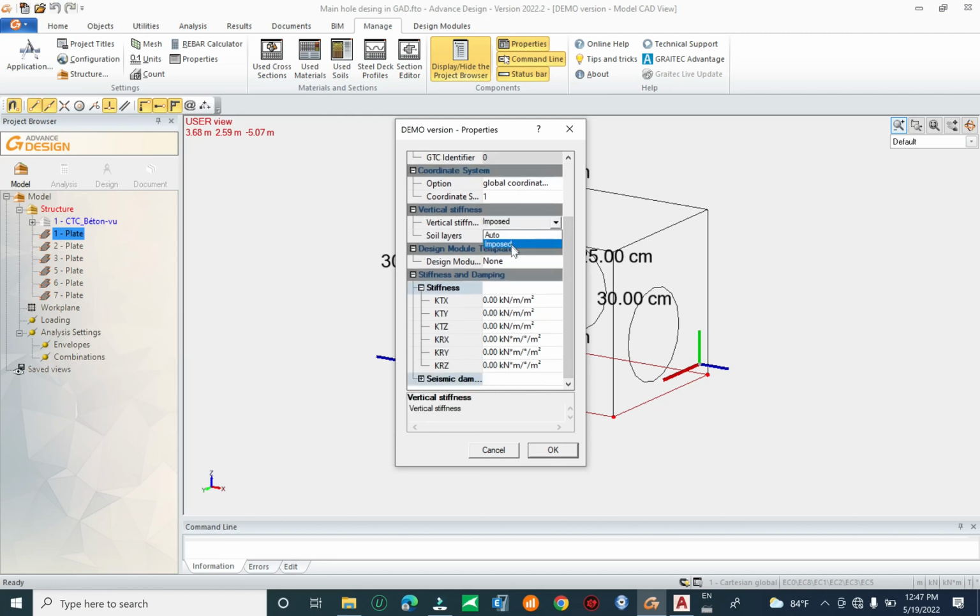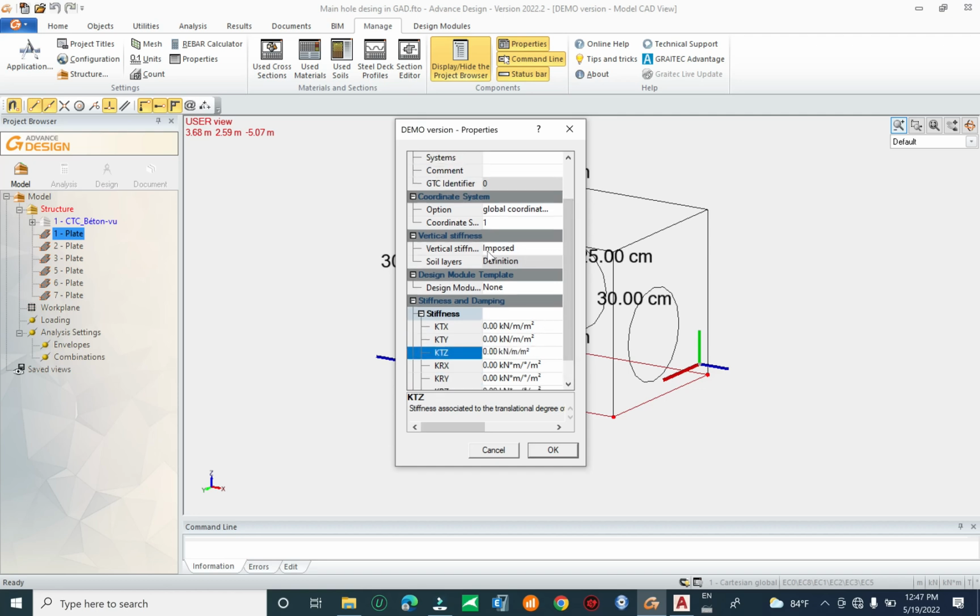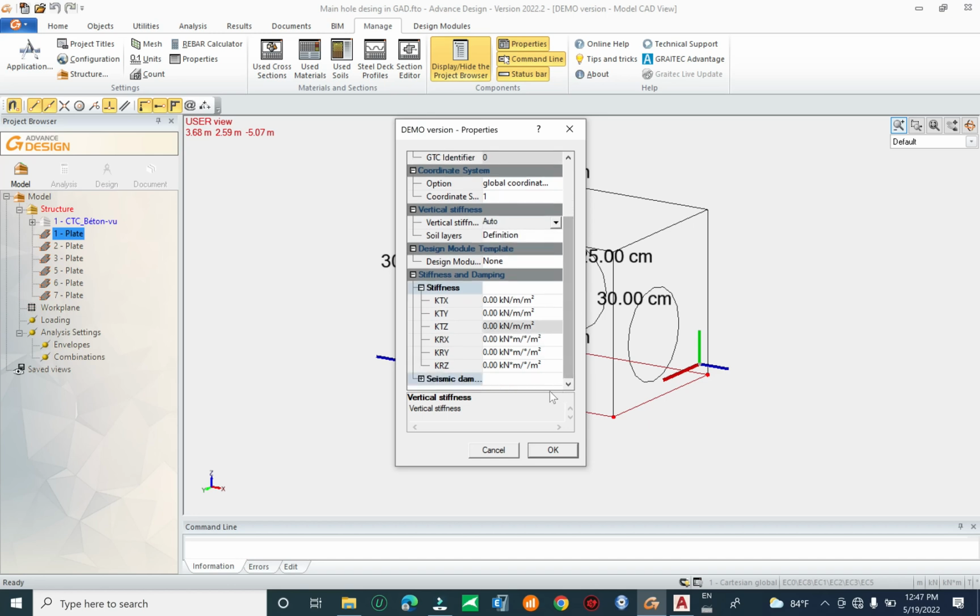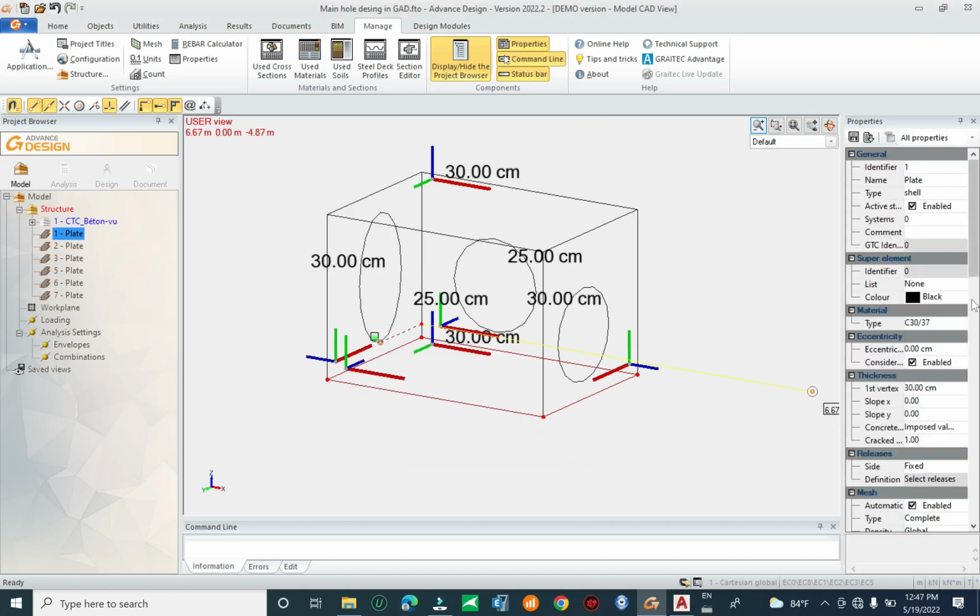Again, click on the bottom slab, right click, support, area selection, elastic, and you can import or auto. For import, you have to input the value or the soil thickness in the direction of the global coordinate, you see here the global coordinate in the K direction. Manually you can input it. Now we have to select the auto value, click on OK.